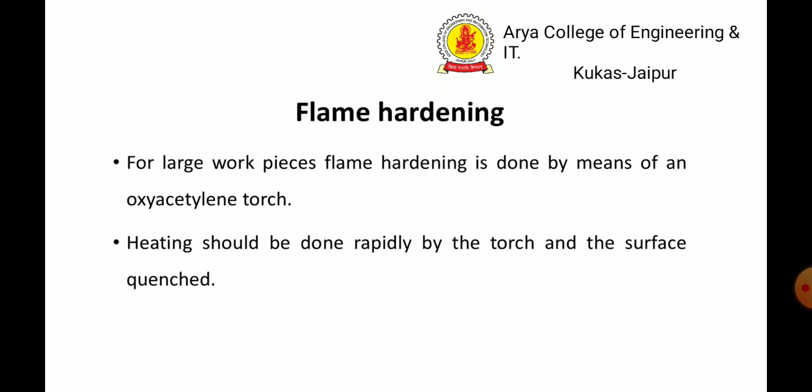This process consists of moving an oxyacetylene flame over a part followed by a spray quench, and the rate at which the flame is moved over the part determines the depth to which the part is heated. Heating should be done rapidly by the torch and the surface quenched.